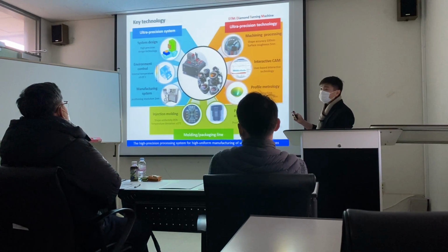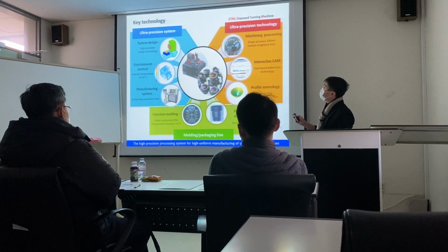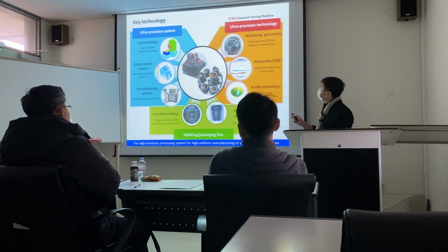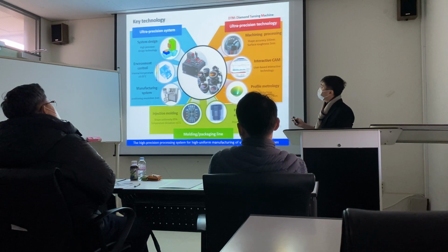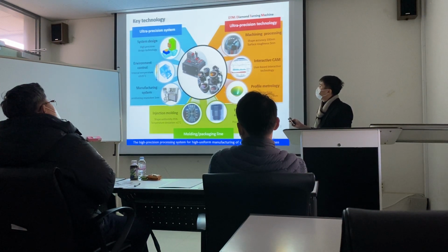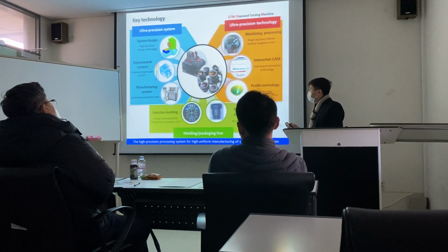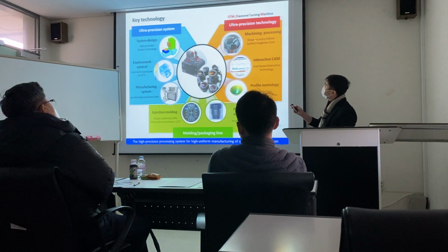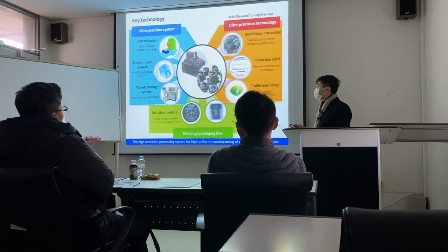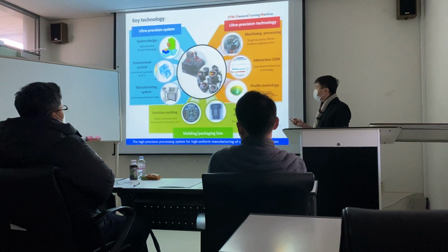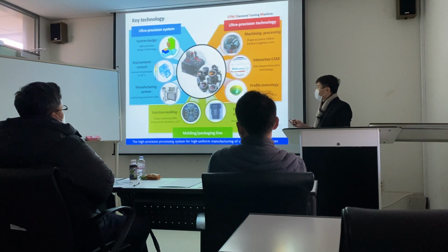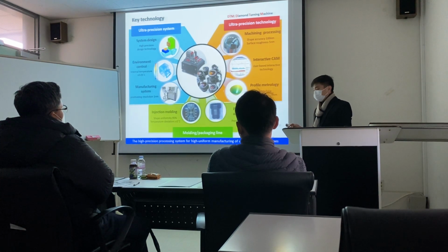The machining process requires a shape accuracy of 100 nanometers and a surface roughness of around 10 nanometers. Combined with the machining process, we have to check the surface by profile metrology. It can be applied to our machine with a sharp accuracy of 25 nanometers RMS.